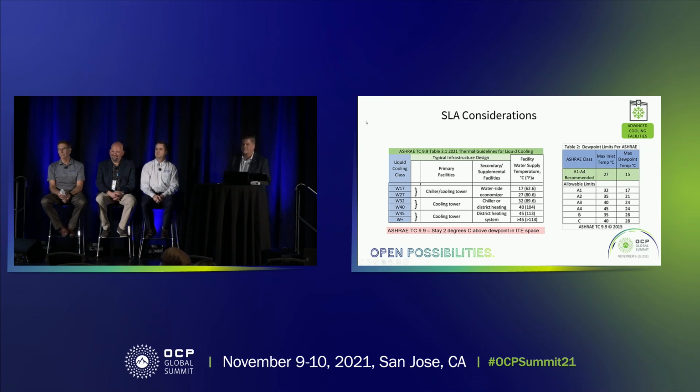Yeah. One quick comment. This is Paul Artman, I was a founding member of TC 9.9, but John did a really good job discussing the new W ranges for water. And we've done a really good job, as an industry, saying this is why you want to transition from air to water. What we have to be extremely cautious about and start working on is saying that W45 is probably not viable. We're moving from air to water, but power is going up at such a high CAGR. You just have to be real careful about the recommended ranges, because I would never advise anybody to do W45.